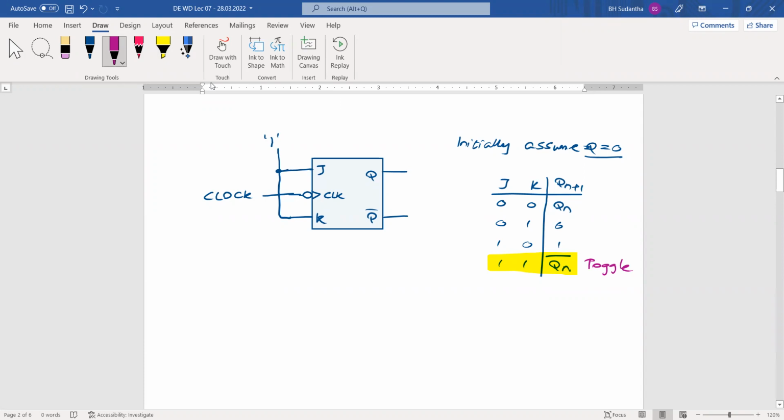After setting 1 1 to the J and K inputs, you can now issue a clock pulse to the clock input. Assuming that initially Q was 0, what is the Q value now? The present Q value should be the inverted value of the previous output. So find the previous output, invert it, and then say your answer.